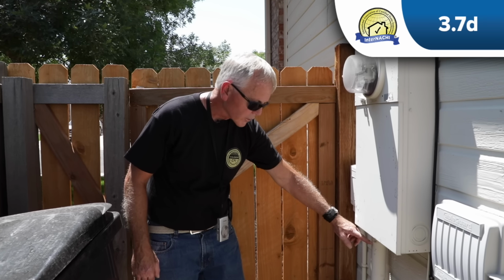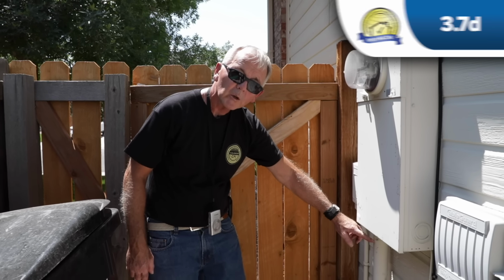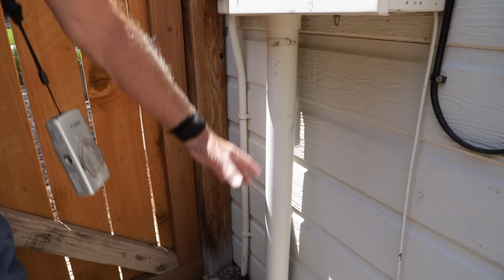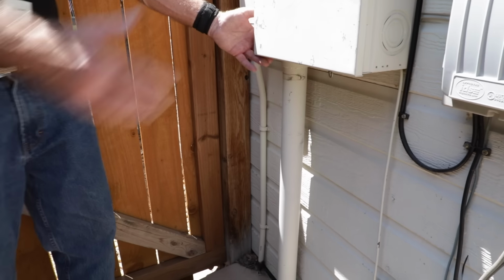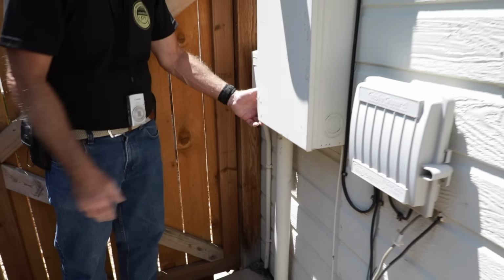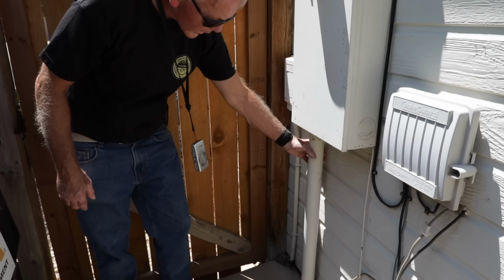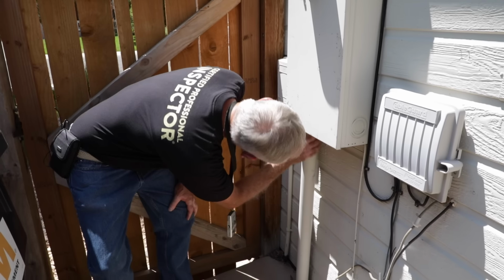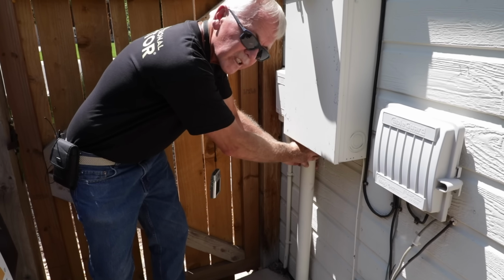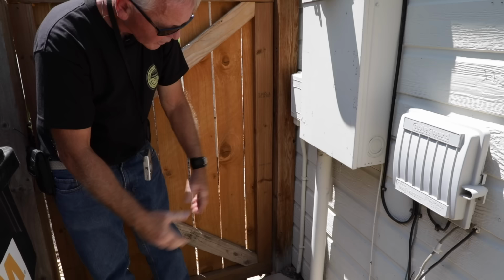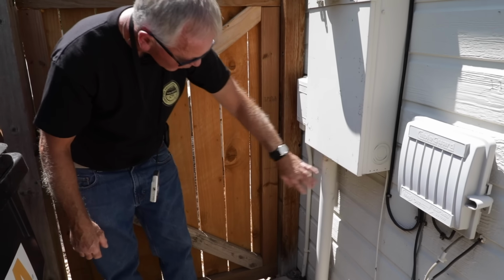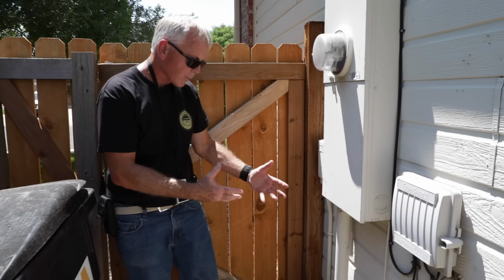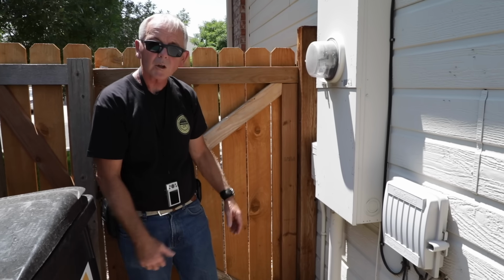We're going to go on to the surface mast, raceway, and conduit. And in this case, we have an underground service, so it comes up from the ground into the bottom of the service equipment. Everything looks secure here. We want to make sure that it's good and solid, that the fitting with the lock nut on it is good and tight. We can't see the conductors inside, so we just have to judge what we can see from the outside. So this is a pretty simple application here, so that pretty much concludes this.